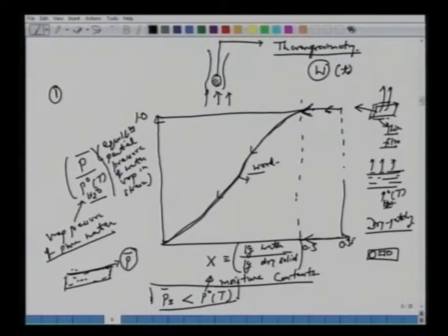All right. So it decreases, and it's going to decrease all the way. You will expect that it reaches a certain level of partial pressure in the atmosphere. So now you are drying with air, and this air's moisture partial pressure, its moisture content, is fixed. So let's say this value is 0.6. So are we plotting P bar over P0T? You should recall from some other class that that's nothing but relative humidity, or relative saturation, RH.